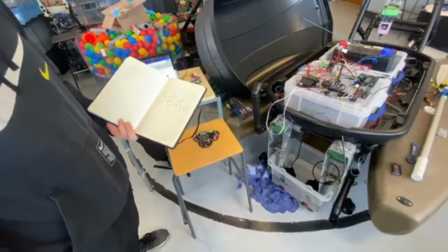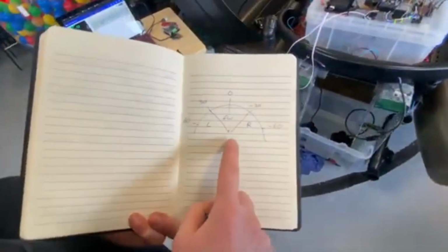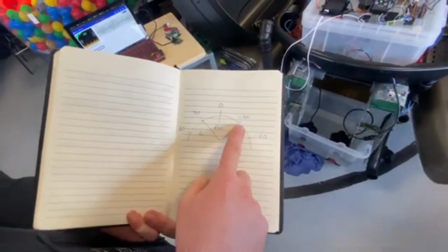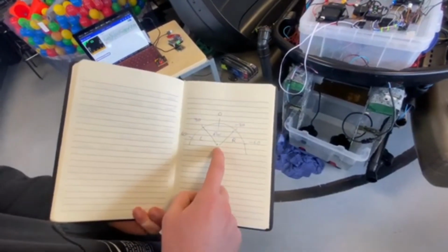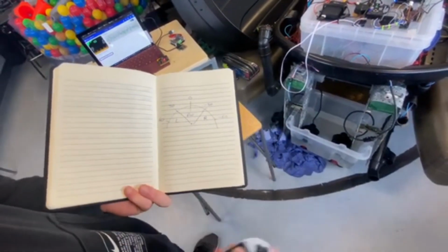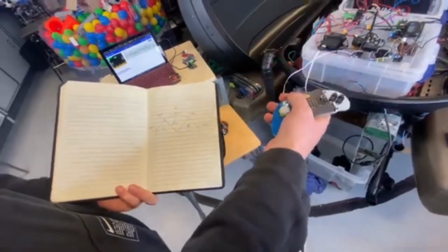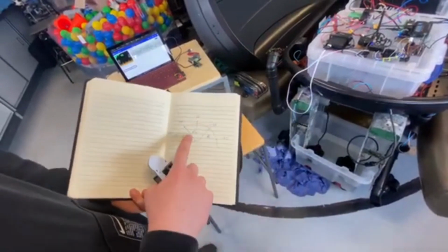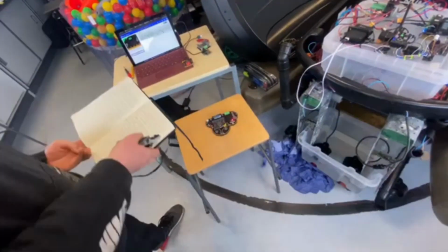And go. So welcome to the auto drive demo of the USV. So the way it works is we have a bandwidth between 30 and minus 30, and if that's the case, the USV will go forward. That's the degree difference between the direction the user gives and the direction the USV is actually facing. So if it goes outside of those, it'll adjust the left and right motor.